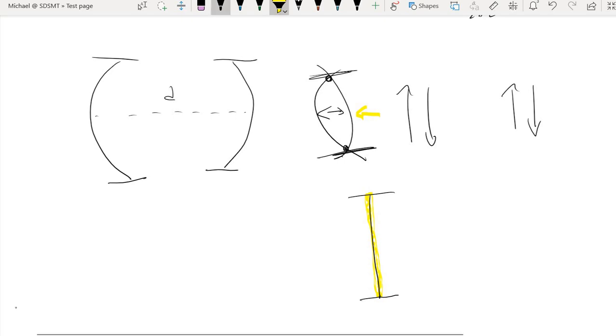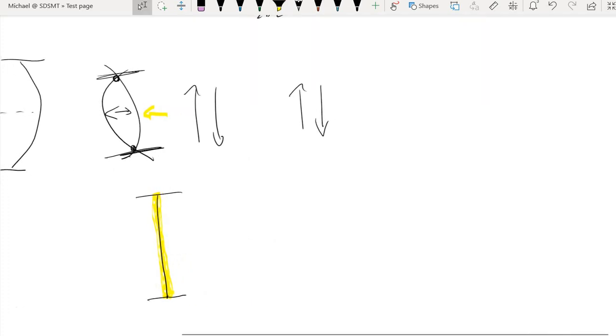And you probably want that conduit to be made of something that's insulative, maybe some PVC pipe, but I guess if the wires themselves are insulated, you could use metal piping, but that really comes down to cost and how much your supervisor is willing to spend on a simple preventative maintenance issue like putting some kind of a brace around the wire.